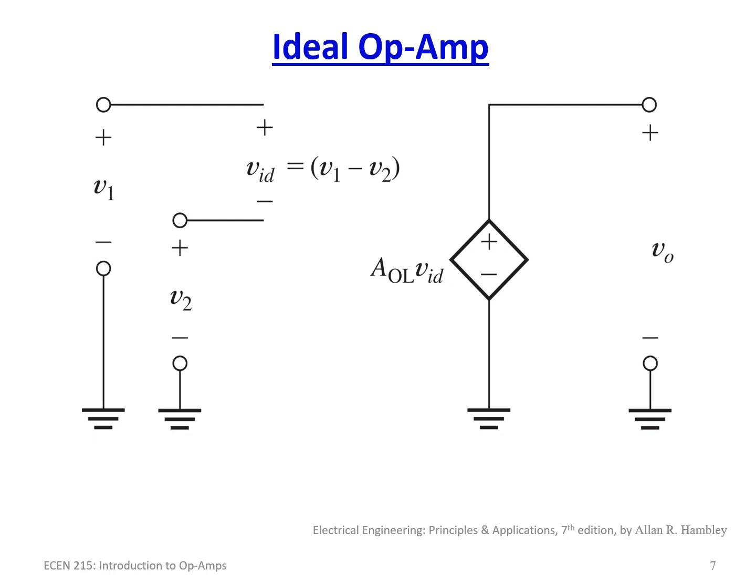This is a dependent source. This, in fact, is a dependent voltage source, and it is dependent upon another voltage, in this case, VID. So we have a voltage-dependent voltage source. And it, of course, uses AOL, which, again, is equal to infinity volts per volt, and it's going to be multiplying that times VID.